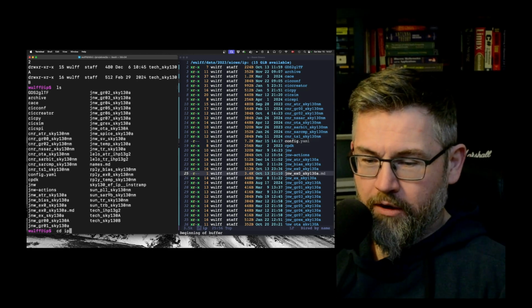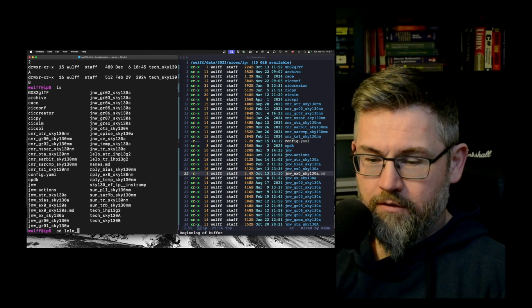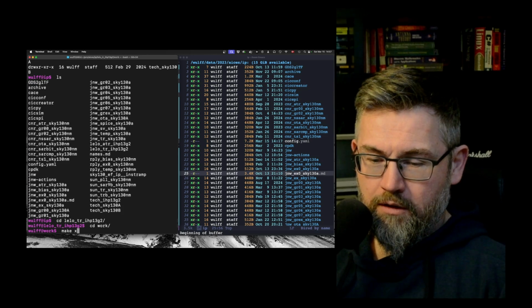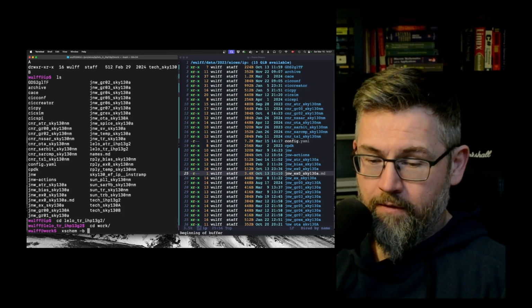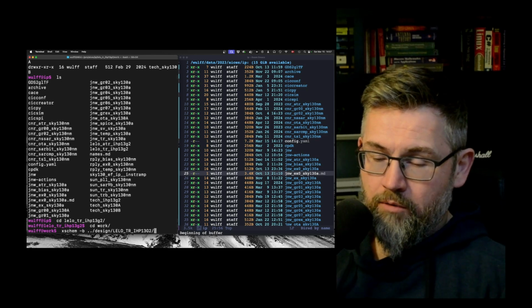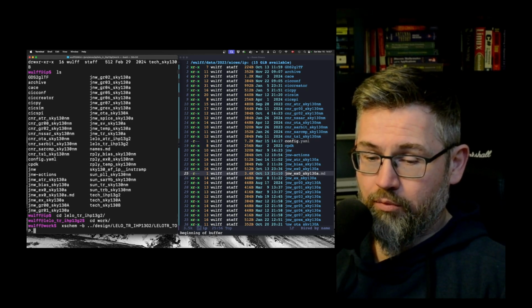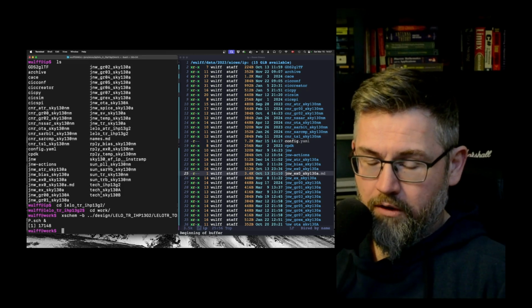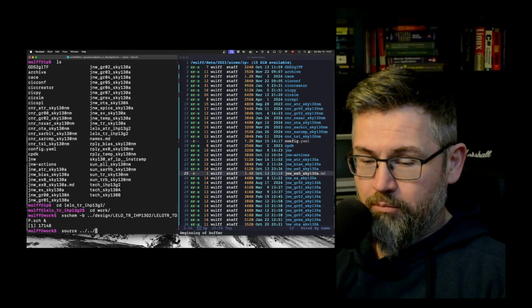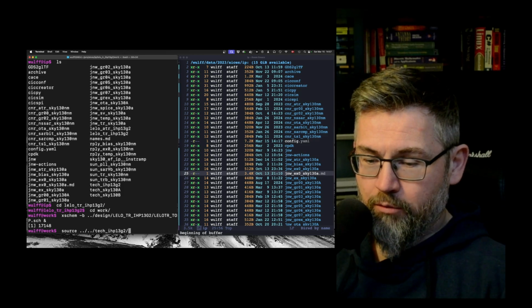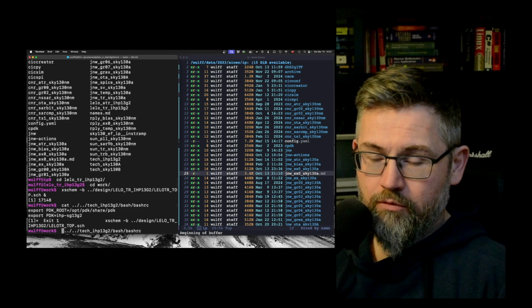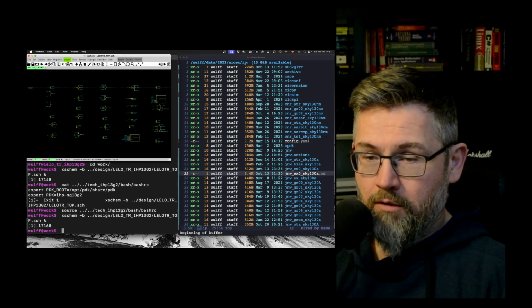So if I go into my newly ported transistor library, let's have a look at what's inside. So okay, let me write the command. And we want top. Couldn't find PDK root. Yes, then I need to set up my environment variables. Let's just see what's inside that. So this just sets up my PDK and my PDK root. Okay, and we need to start that.